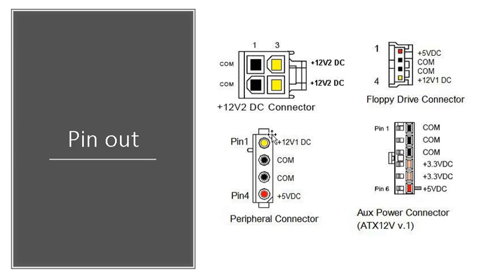Another way to see it is with the color. So you have the yellow color as pin 1 and 12-volt. If you think that one of them is failing, you can use your DMM, and you can measure what voltage you're getting from each one of the pins and see if they are at the actual voltage. And if yes, then you go forward to look for other parts of the problem. But pretty much this is the first step that you want to do when you want to troubleshoot your power supply, to see if all the connectors work or not.